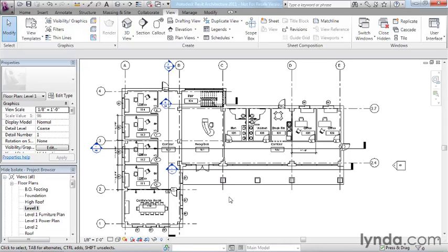And the way this works is when you select the item and you say, I want to hide it, it hides it permanently until you choose to go and unhide it. So it would print that way, and it would still be hidden tomorrow when you open the file. So for example, while I was working on the curtain wall, I went in and cut this section here along the front of the building just to make it a little easier to see what I was working on.